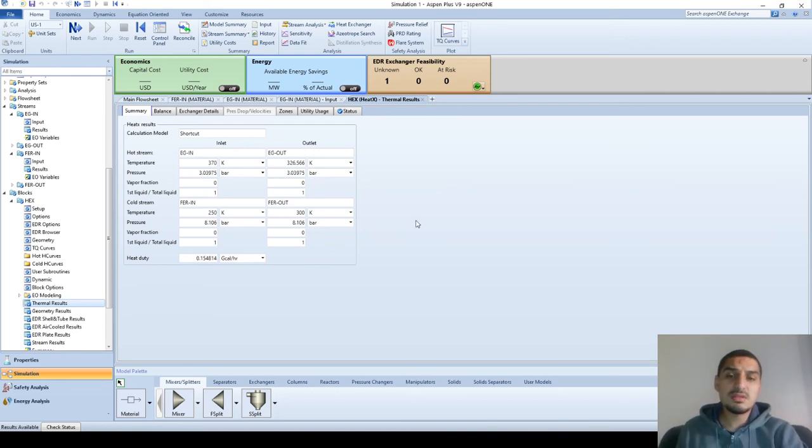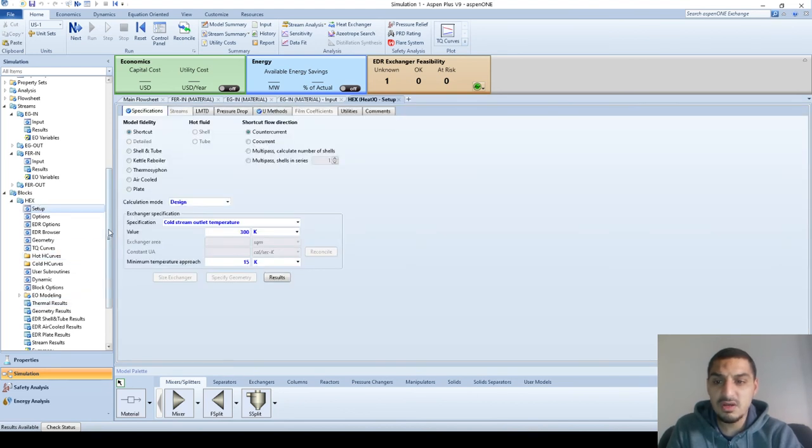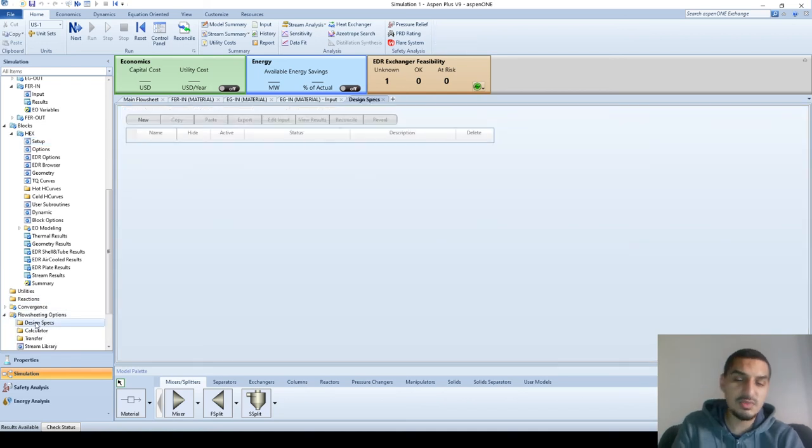So there is one last thing that we need to do, which is to change the flow rate so that we can get this 315 as we want. And to do this, we can simply decrease the flow rate of the ethylene glycol and see how this will affect the exit temperature. But this is gonna be a time-consuming thing, so we can simply use one other feature in Aspen Plus that we used before, which is the design specs. We have already used it in the flashing, if I recall right.